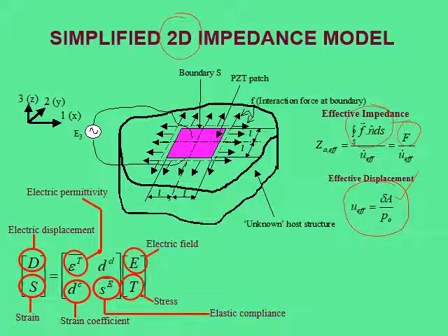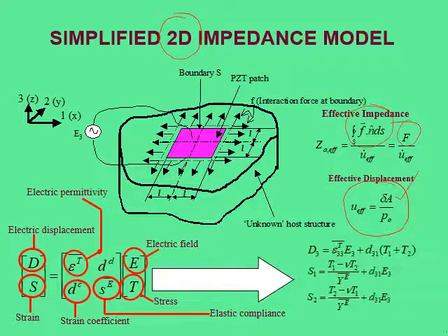So this helps in deriving another equation. By using the 2D piezoelectric relations, the direct effect and the converse effect, all we have to do is use these equations in the case of 2D, and then we get this kind of expression. Here, what we found is that the charge is now a function of both the stresses in the two directions, T1 and T2.